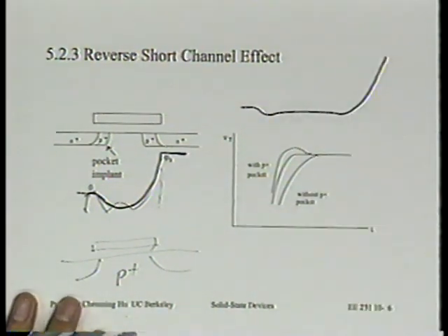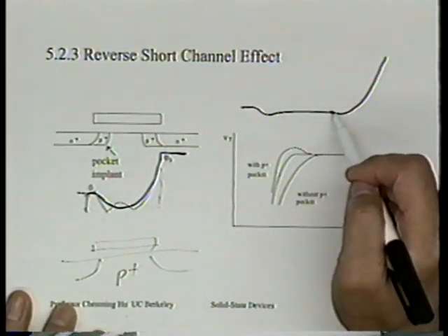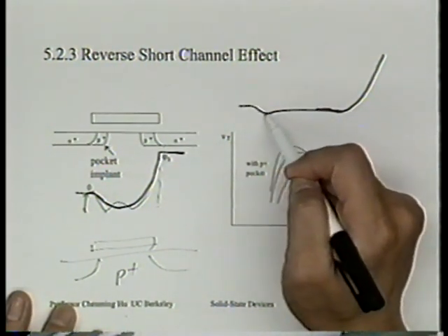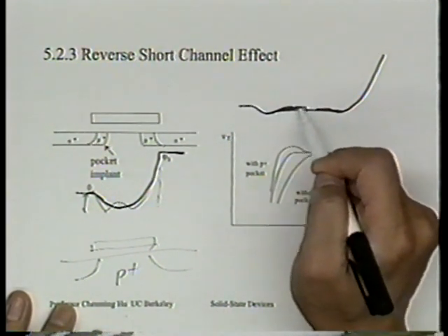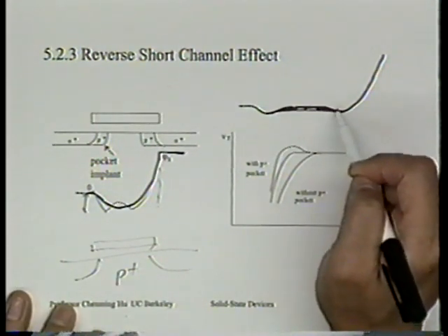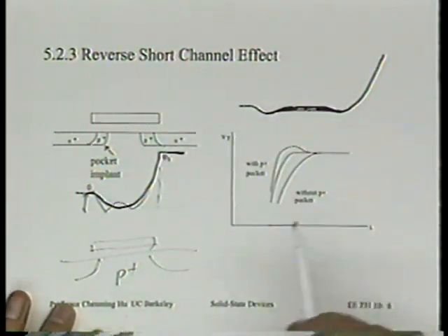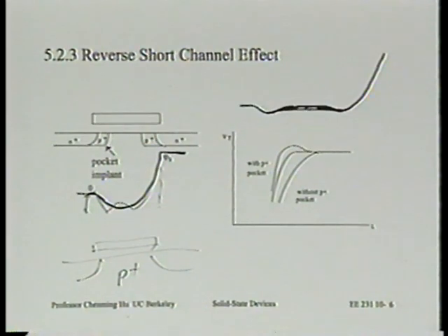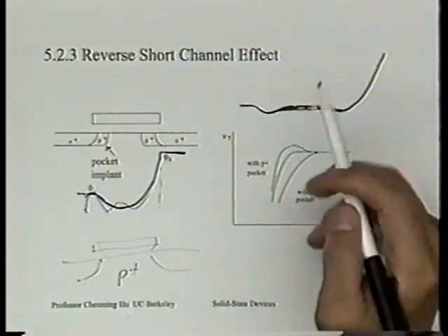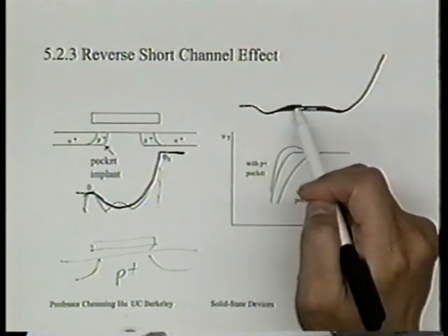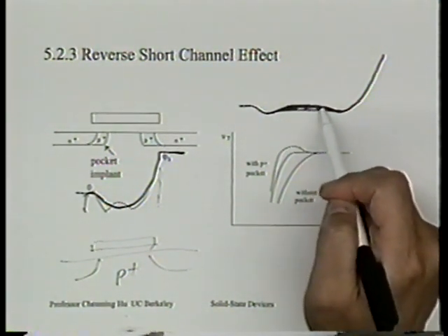We might have a picture like that. There's some effect due to the doping. I'm not trying to say there is no effect at all. There definitely is an effect, okay? That's why even for a long channel transistor, by adding this pocket implant, you will notice already VT is a little larger than without this pocket implant. You can probably believe me, all right? And certainly technologists will know that sometimes people have difficulty accepting that.